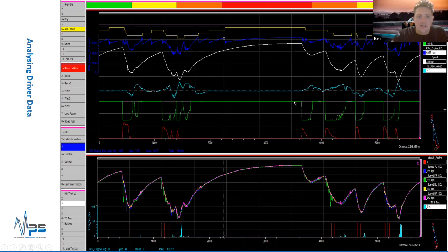So unfortunately, this Bentley is littered with sensors. So I've got all the luxuries as well. If you see the next sheet, it's a duplication of the type of graph. There's another time distance graph, which I'll talk about shortly. But this time it's filled with just wheel speed sensors. So you'll see I've got each corner overlaid on top of each other. So it makes it really easy for me to see when a wheel locks up, for example, like this green one here, or if you're struggling for traction, like you can see the pink is going faster than the blue down here.